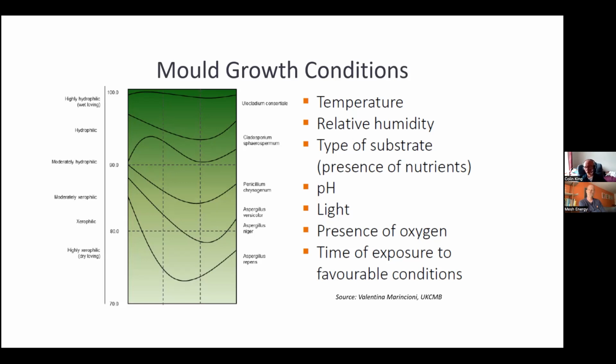Mysteriously, the rising damp problem goes away, and it doesn't cost you £3,000 for a whole dose of unicorn oil in your wall. And it's exactly the same with mortar. If you've got a lime mortar which is vapor open, it's got very high levels of porosity, and it's very soft. If you then put cement over the top of it, the cement is too hard, and then what you get is micro movements at the interface of the lime and the cement, and water gets behind it. So the water gets behind the cementitious material.